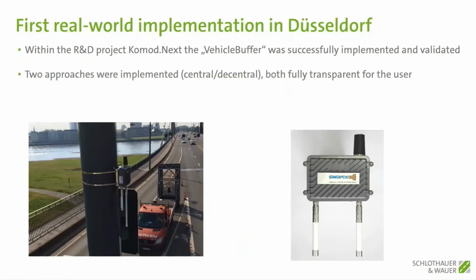Next, of course, it was a good year last year. We had the first real-world implementation done in Düsseldorf, Germany, where we put the concept of the vehicle buffer directly in the Lisa signal control, connected it. It was an Actros controller from Swarco, and we connected that to a roadside unit also from Swarco, and of course there was a connection to a traffic management central. So what we've shown there is that we can run two approaches at the same time, the central and the decentral approach. And the great thing here is that it's fully transparent to the user.